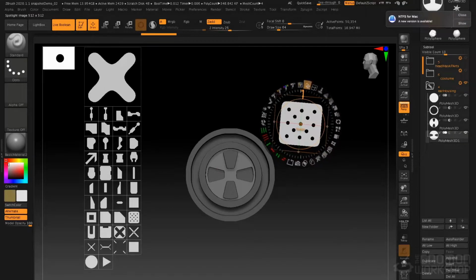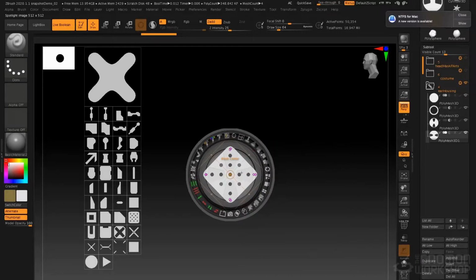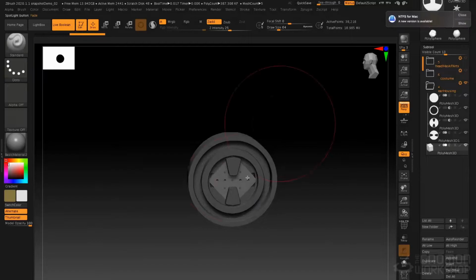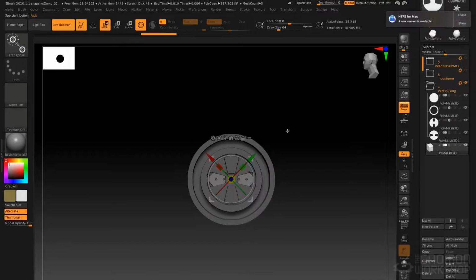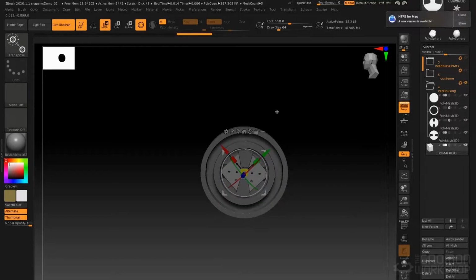snap to the image center, scale it up, and I'm going to rotate it, but hold the shift key so I can snap it to increments. And then this will snap to the mesh center there. And we can dial this down. And I'm just going to make that an additive shape, just like so. Now, if I go to my gizmo, I can pull this forward. I can scale this to make it thinner. I could put it behind that other shape. I can bring it forward so it's this sort of panel sitting underneath these two tabs.